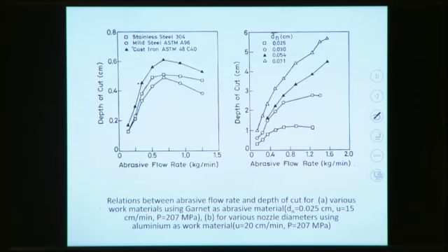So here we can see that with increasing abrasive flow rate, the depth of cut rate is very high here. After that it touches the optimum abrasive flow rate, where your depth of cut is maximum. After that, the depth of cut actually decreases when we increase the abrasive flow rate.